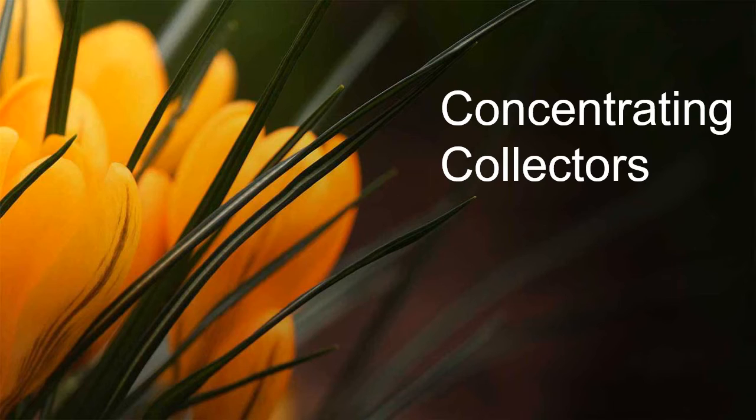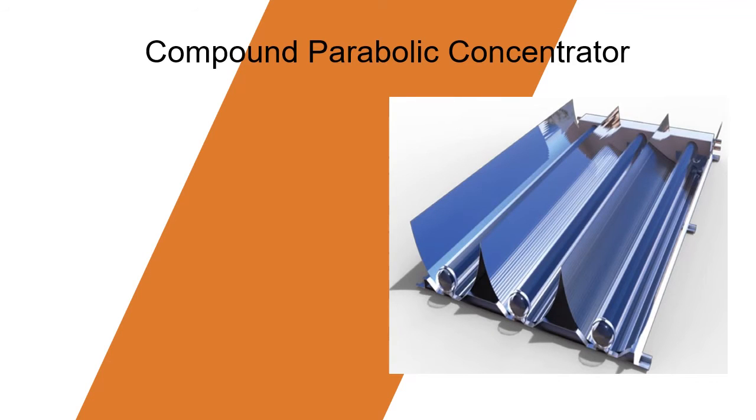Solar thermal power plants utilize concentrating solar collector systems because they can produce high temperature heat needed to generate electricity. These collectors can also be classified into non-imaging and imaging, depending on whether the image of the sun is focused at the receiver. The concentrator belonging in the non-imaging category is the compound parabolic collector, or CPC, whereas all the other types of concentrators belong to the imaging type.